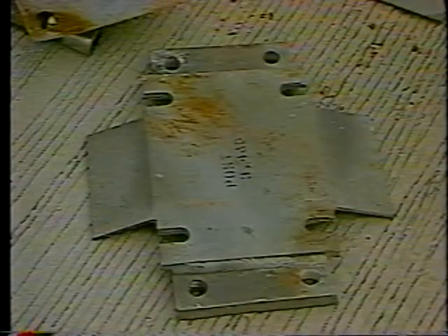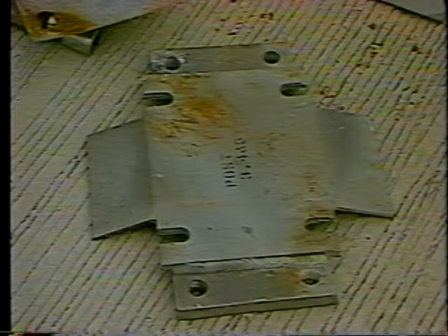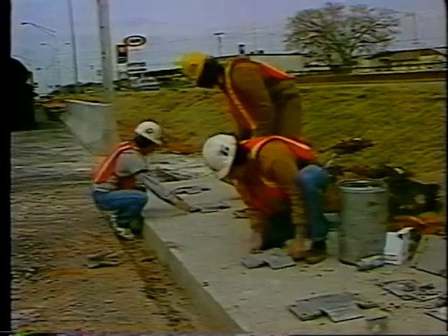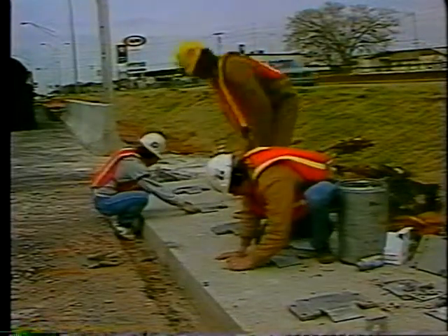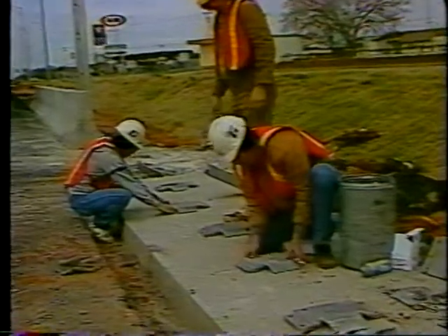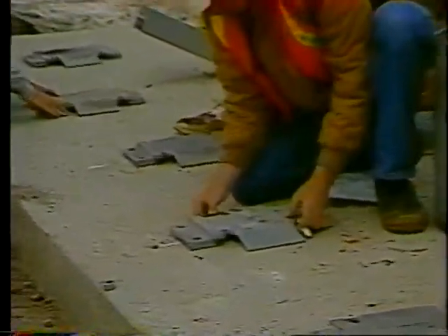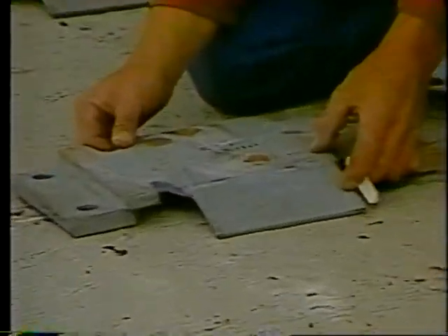2 types of slip bases are supplied for the unit. The slip bases for posts 1 and 2 have flared slots, while the slip bases for posts 3, 4, and 5 have straight slots. Arrange the bases next to the proper post locations with ramp ends touching the ground before proceeding to the anchoring process.